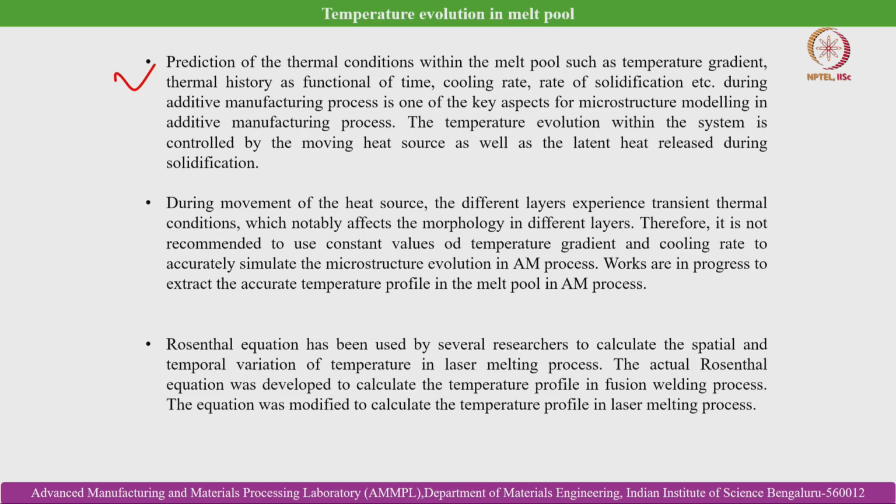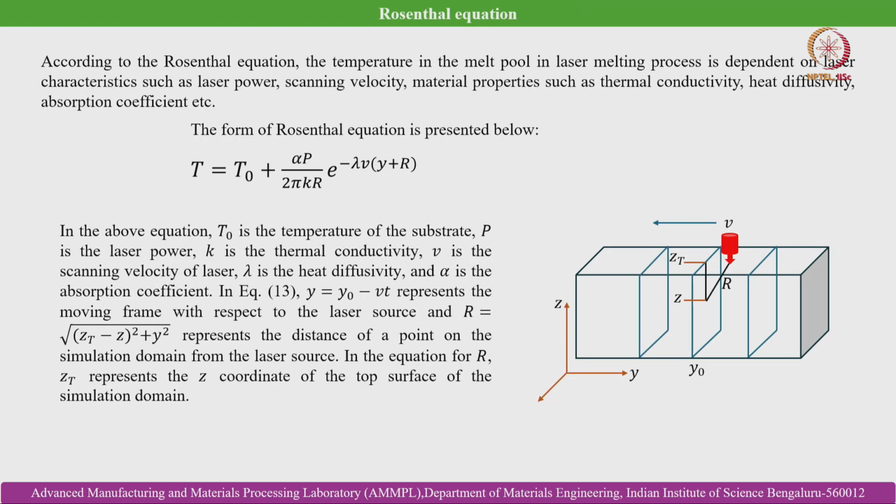Presently, efforts are underway to couple the phase field model with the CFD based process model that we are developing, because in that case the CFD based process model can predict the temperature distribution within the melt pool, and that temperature distribution can be utilized by the phase field model to predict the microstructure evolution in the region.